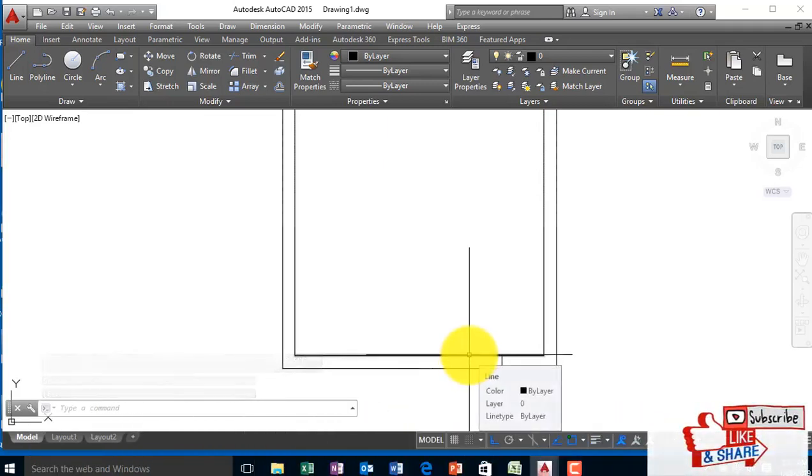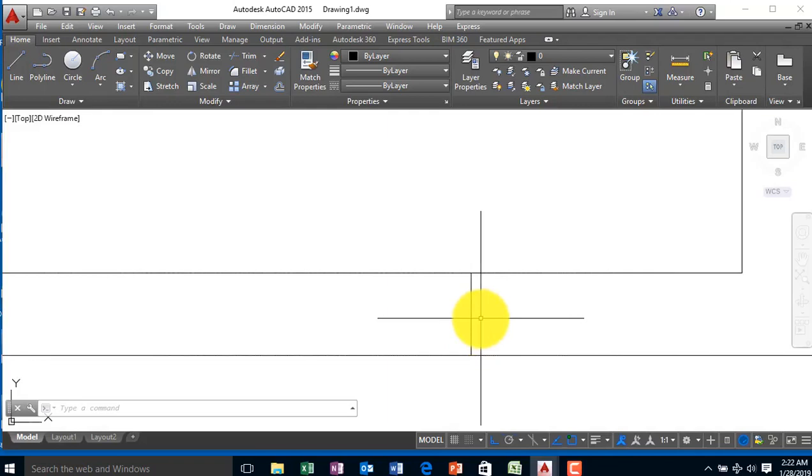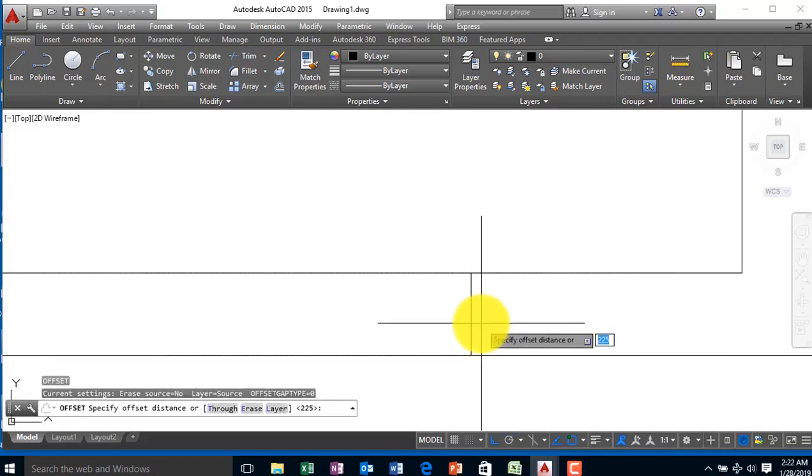All these you get familiar with them if you go and study the architectural designs. You know the standard dimensions of a door, which is about 2.1 in elevation, the width is about 800. Some doors are 750. So the next thing is for me to offset this line. Click on offset. I want to offset it 800 mm.